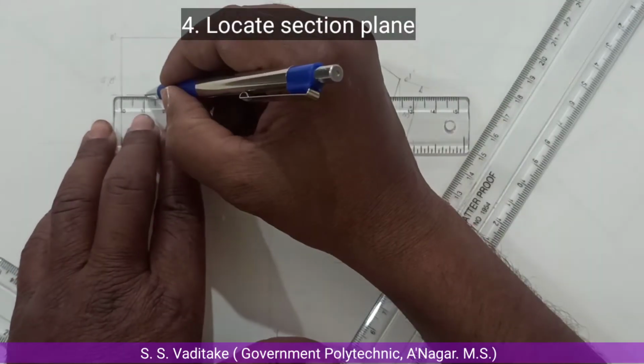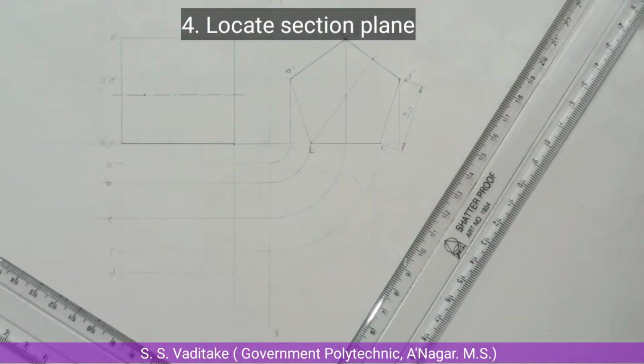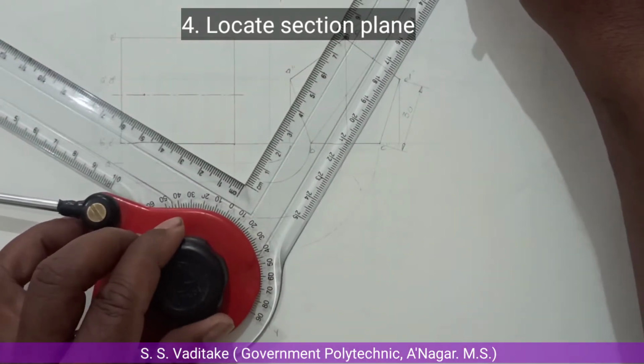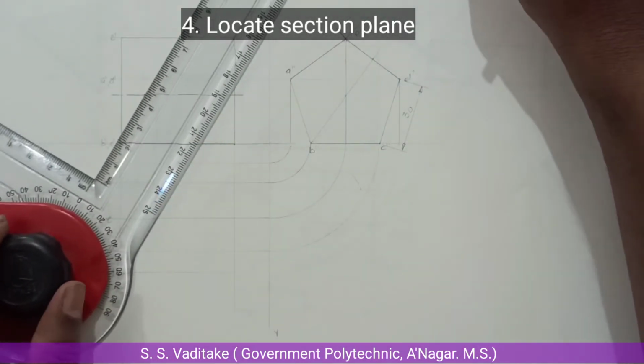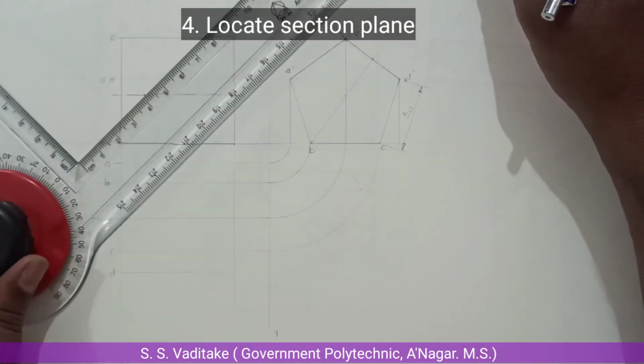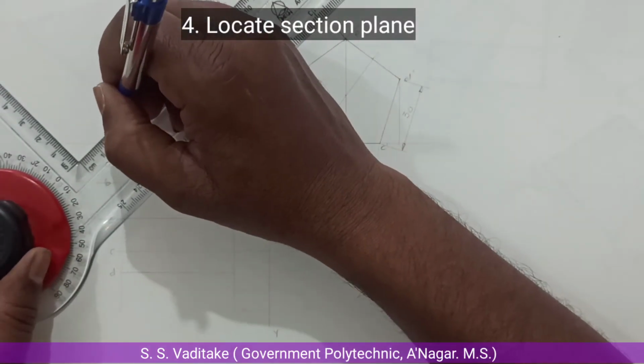So consider the left side base in the front view. Mark the 10 mm distance along this axis. Now through this, draw the section plane which is inclined at 45 degrees.